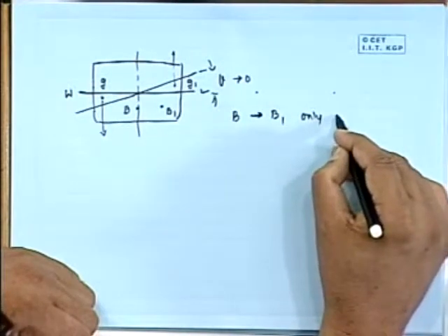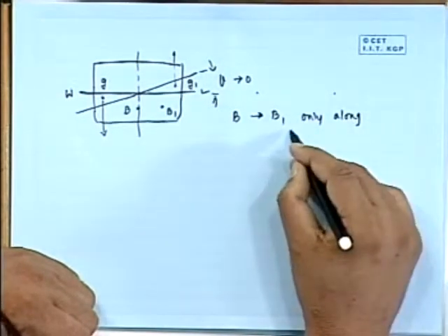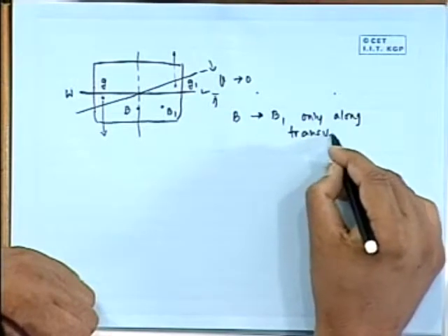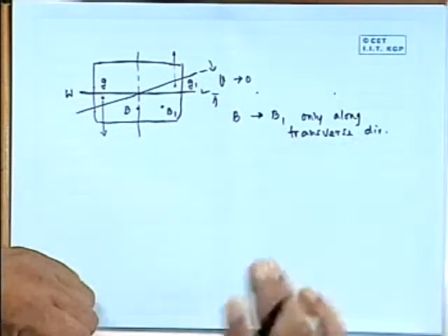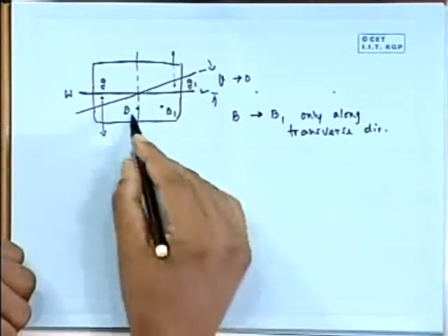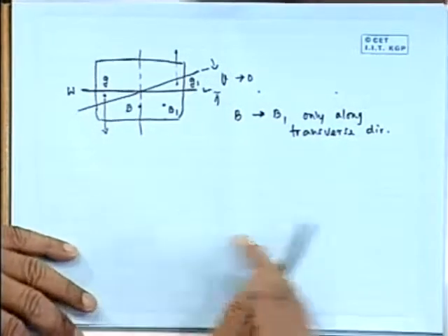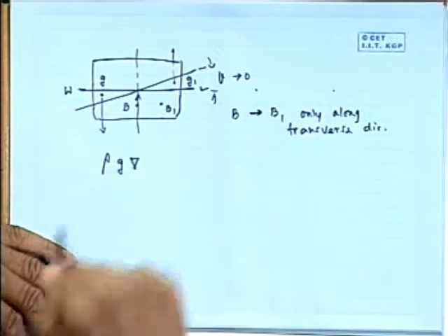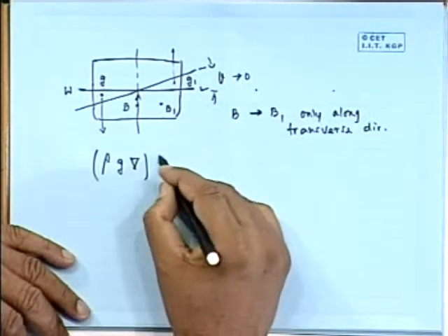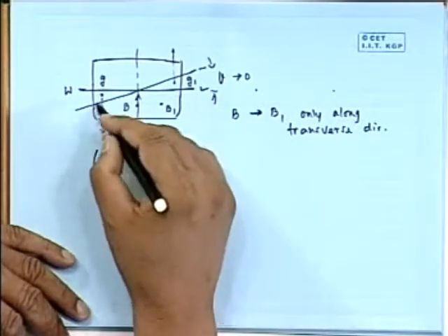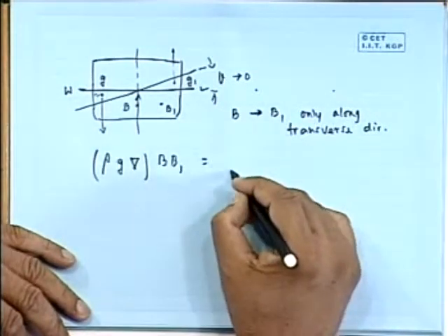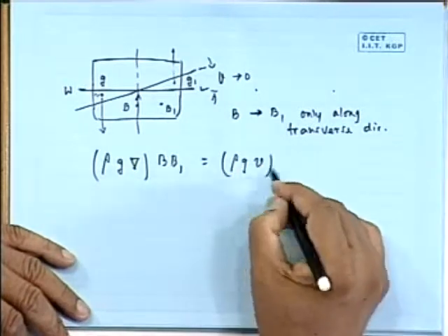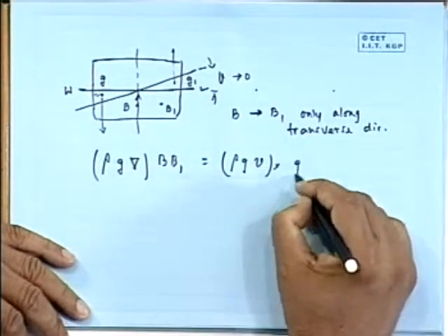only along the waterline, or let's say the transverse direction. No vertical shift. The question is, how much is the shift now? Obviously, this can be very easily figured out by using moments. If I take moments now, there is a buoyancy acting through this of rho g times volume. This multiplied by B to B1 should be equal to the volume of this slice, small v, into G G1.